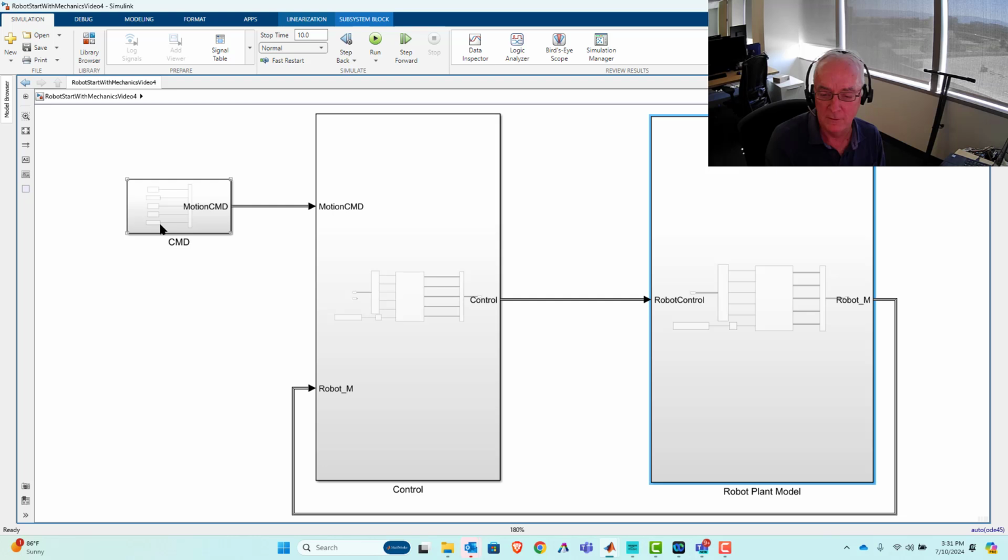As soon as what we think is happening in our controller, basically what we set up in our command signal here, departs from what's really happening, all the calculations of ideal torques will be gone. It's not a good calculation at all. And that's the point of feedback: let's make sure that what's really going on in this robot is continually informing what the controller is doing. That's the nature of feedback, and it's why it works so well.